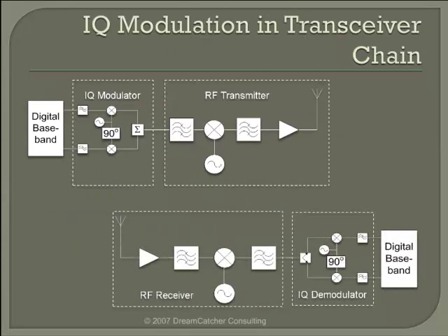Earlier, we had learned about several important reasons for modulation, which is to upconvert the signal to fit into a suitable antenna size and percentage bandwidth, and to enable multiplexing. Hence, to complete our transceiver chain in a communications link, an RF transmitter and receiver needs to be added to our system. The RF heterodyne transmitter upconverts the intermediate frequency, or IF, from the IQ modulator to an RF signal suitable for wireless transmission. Similarly, the RF receiver side downconverts the received RF signal to IF.